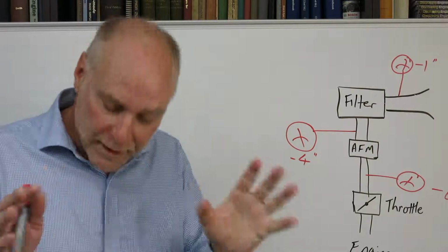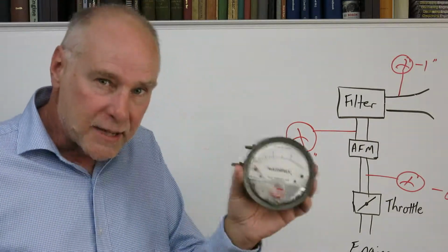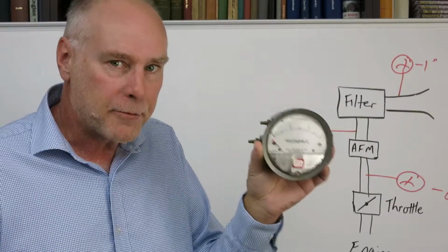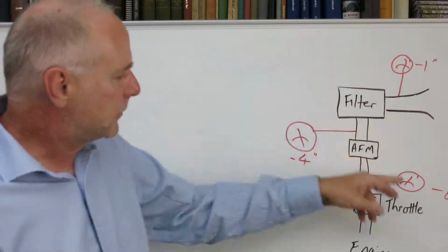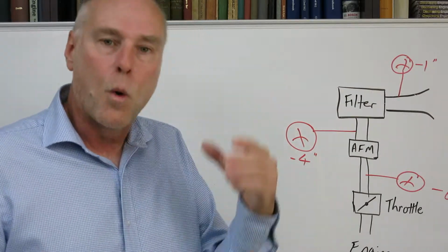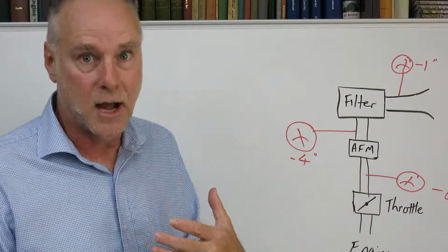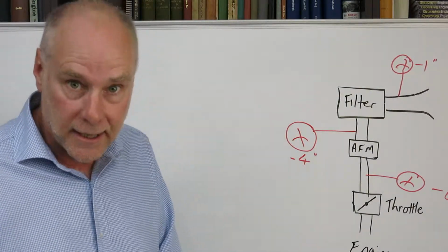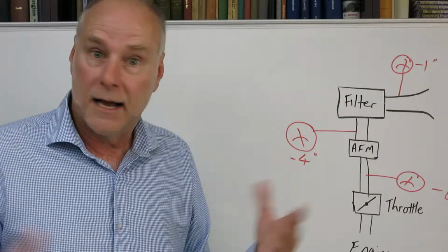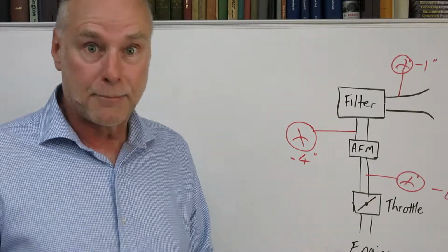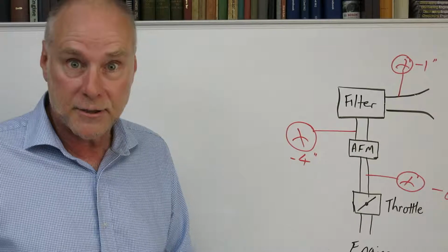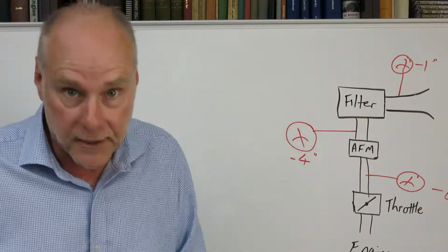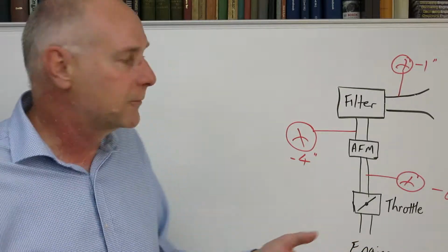So we can use a gauge to measure through the intake system at a succession of points what the peak pressure drop is. By doing some very simple subtraction, we can work out which components on the intake system are causing most of that pressure drop, and then we can look at improving those particular areas. So for example, in many cars, believe it or not, the intake to the airbox is too small. It's causing a pressure drop. And if you fit a larger intake to the standard airbox, you'll see often an improvement. And you can measure, of course, what that improvement is.